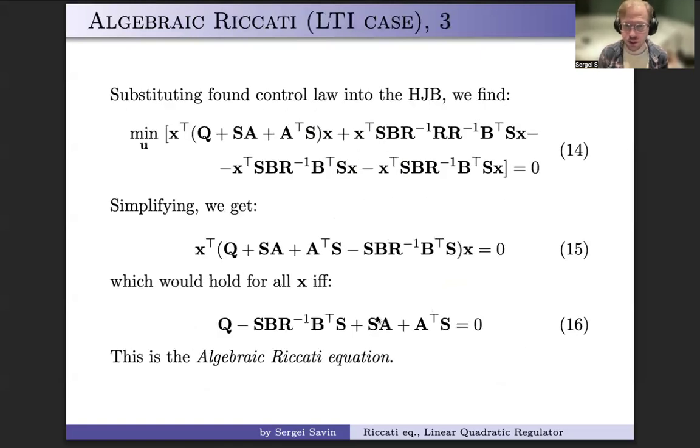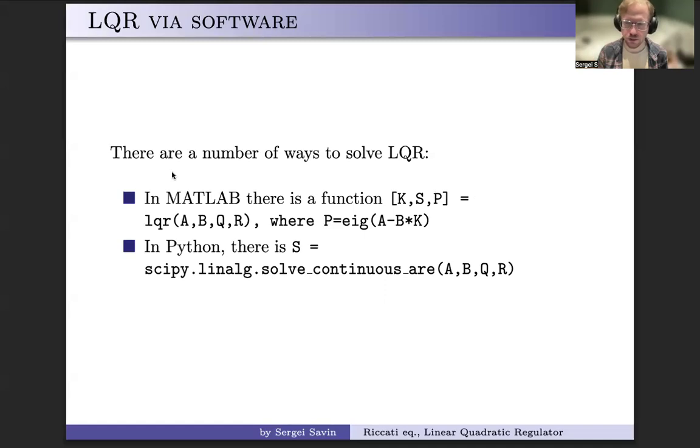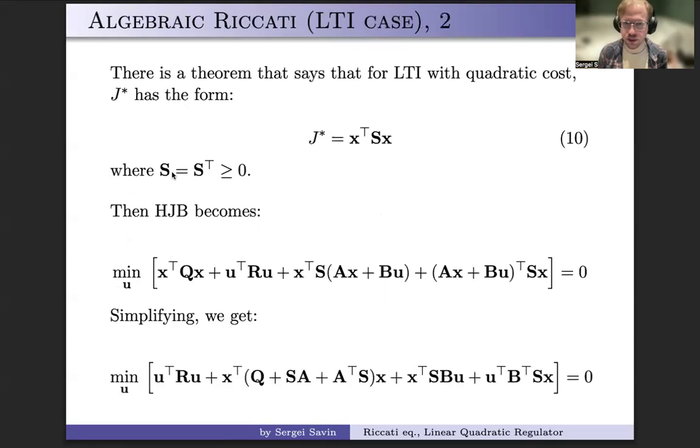And as a result, you'll get what we call a differential Riccati equation. So this guy would be different in one term. There will be minus s dot here, if I remember right. And you would get a different method called TV-LQR, time variant linear quadratic regulator. Essentially, by understanding this process, you not only understand the one method, LQR, you understand the whole range of methods. You can do LQR on affine systems. Derivation is roughly speaking the same. You can do LQR for different costs.